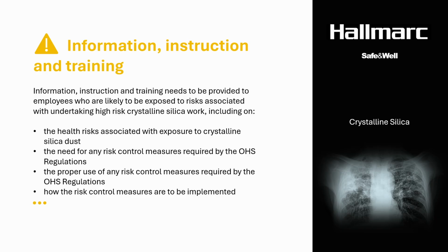Information, instruction, and training needs to be provided to employees who are likely to be exposed to risks associated with undertaking high-risk crystalline silica work, including the health risks associated with exposure to crystalline silica dust, the need for any risk control measures required by the OH&S regulations, the proper use of any risk control measures required by the OH&S regulations, and how the risk control measures are to be implemented.